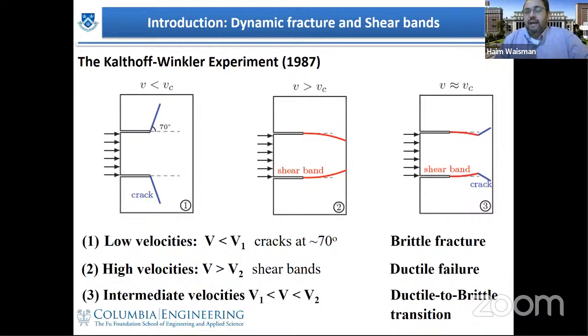The damage evolution law will automatically initiate the phase field at certain locations, similar to damage mechanics. It's different from discrete fracture, where one has to introduce the initiation of a crack. There you have an evolution equation in the phase field, and if the stress reaches a certain critical point, it starts evolving there.